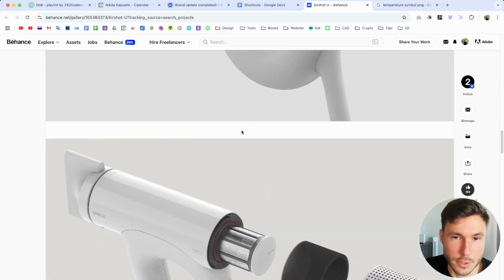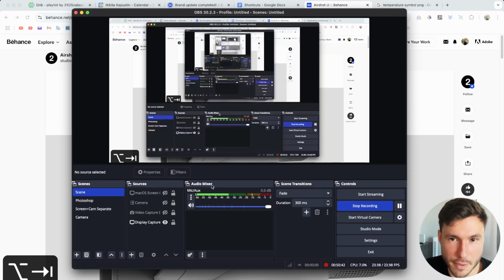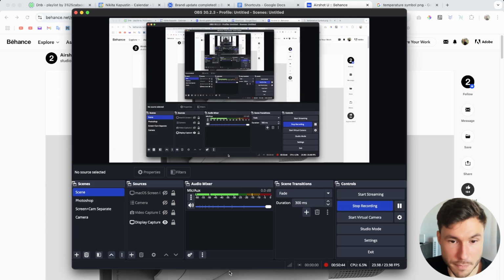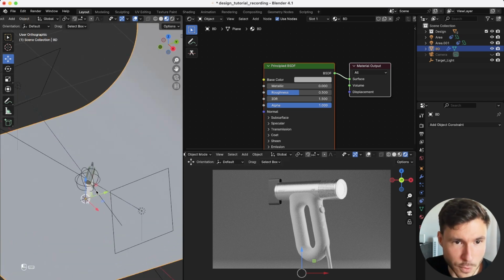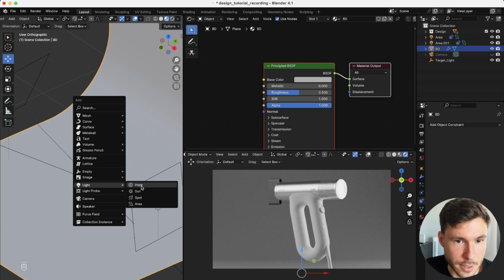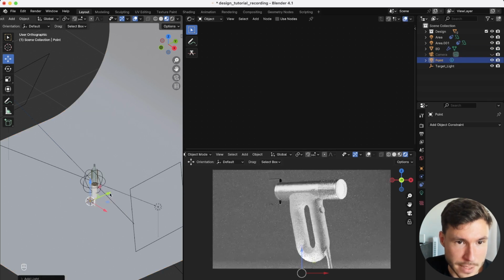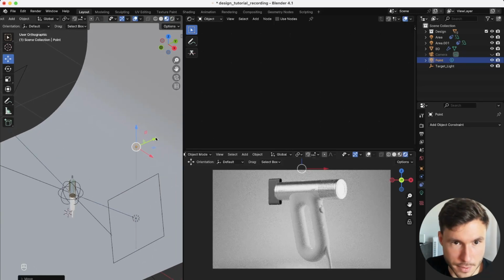I will do it a little how I like it more, because here it's super simple, everything. It's still fine, but I want to make it a little more spicy, you know. So make it a little bit darker. And what I want to do is press Shift A, light, and point light. This point light you just bring to the background a little bit.